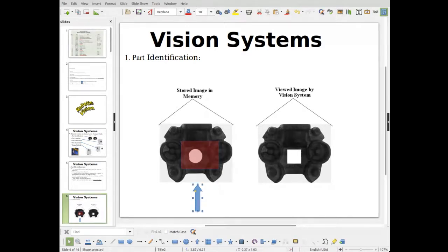So if I throw this mask on the center, then these two parts now become identical to the robot, because I've masked out that center part, which is obviously different. I'm saying ignore it. I don't care. As long as the outside edges and the things that are not masked are viewable, it's okay. The part is what I'm looking for.